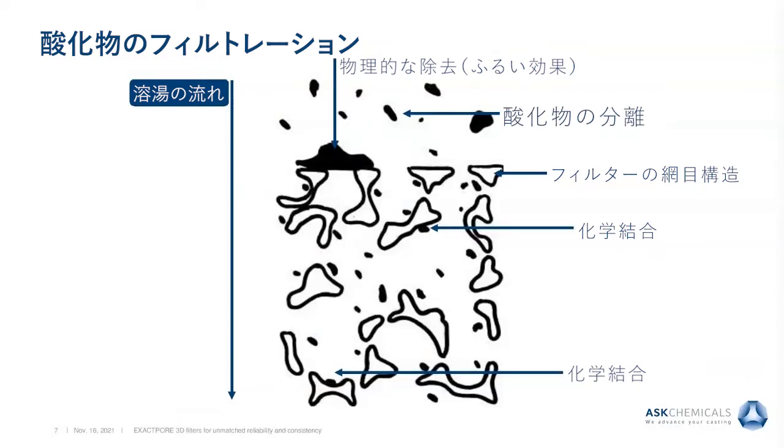Secondly, oxide segregation is allowed due to the fact that oxides typically are less dense than the metal being cast. This density difference creates a buoyancy that, due to the pressure drop of the reticulate filter, allows segregation of these oxides in the runner system or the reservoir above the filter.